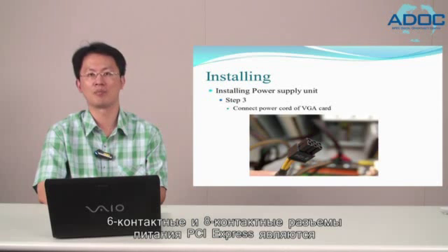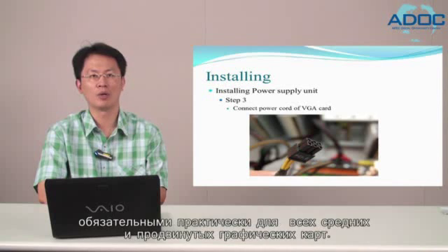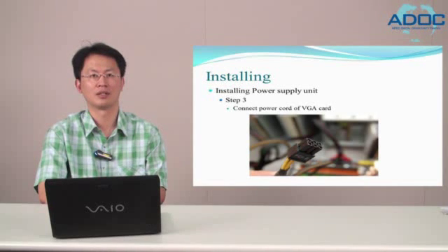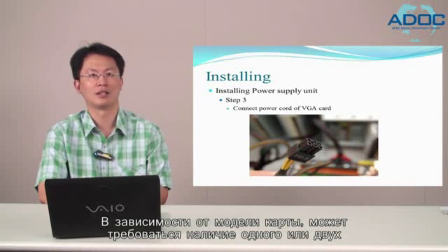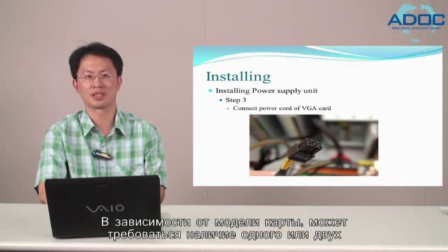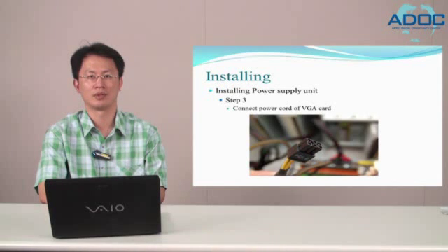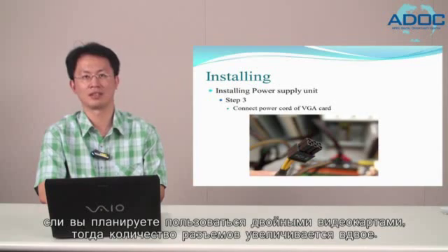And 6-pin and 8-pin PCI Express power connectors are almost only ever required by mid to high-end graphics cards. Depending on the model, a card may require 1 or 2 6-pin connectors, or 1 6-pin and 1 8-pin. If you plan to run dual graphics cards, then this is obviously doubled.